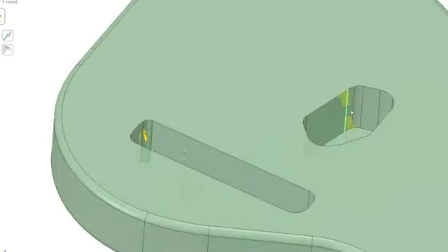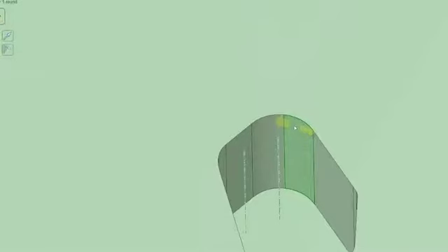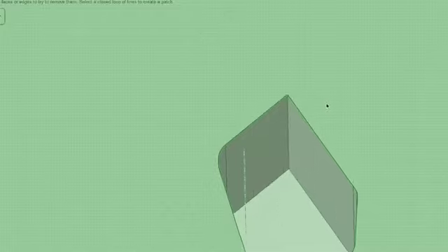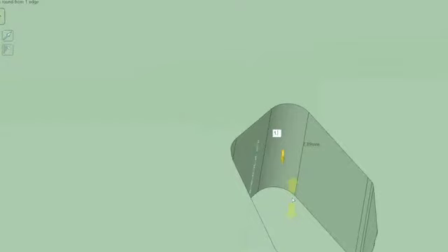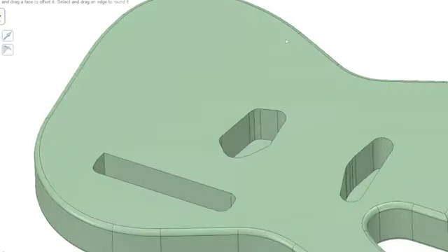Also, you can tell in this other pocket, maybe I have a couple arcs coming in as a blend in the corner. I can use the fill command. I can select both of those faces and say to fill that, and remove those, and then maybe grab the pull command, select that edge. Let's do it as a 10 millimeter. So you can see it's very easy to select and modify the geometry.